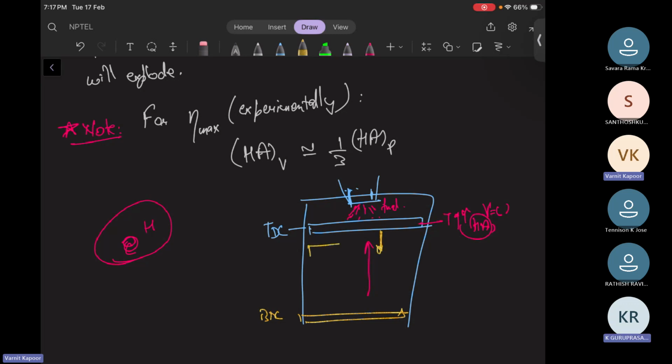When the piston is trying to move from position A to position B, the fuel supply is still there. Fuel supply has not stopped. So here the pressure has been maintained at that instant, and the heat is again added, because once the piston has reached TDC the pressure is maximum, and when it is going down, the cylinder inlet valve and exhaust valve are both closed, so pressure is still maintained.